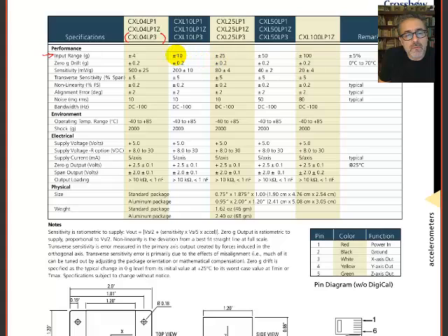You make them stiffer to protect the sensing element. So they're made to handle higher vibration, higher shock, for example. The reason I chose this for the lab is because what we do in this instructional lab is learn how to use these. We don't want to excite them too heavily. We want to also see a response when we shake them lightly so that you can learn how to use them. But think about it, plus or minus 4G, that's a nice human-scale vibration, and so that's why I purposely chose these.